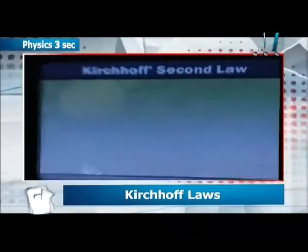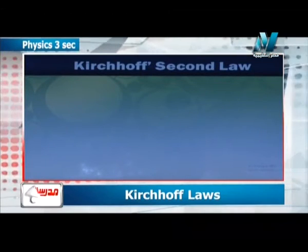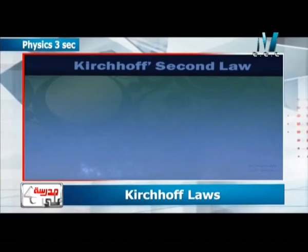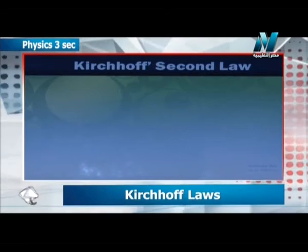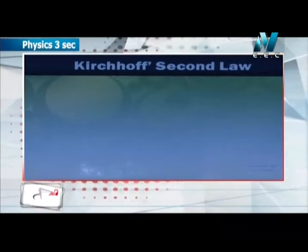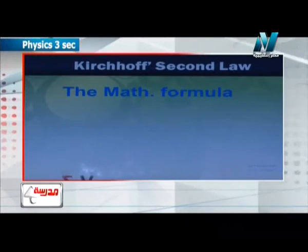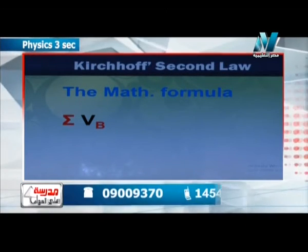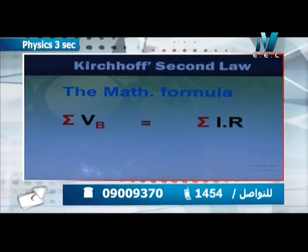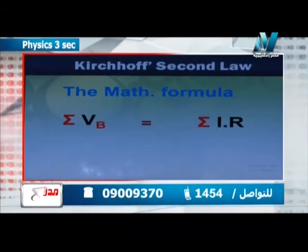What about the mathematical formula of Kirchhoff's second law? Very important question in the final exam. Each year he asks to write the mathematical formula of some equations. Okay, if he asks you to write the mathematical formula of Kirchhoff's second law, you have to write the following: sigma VB equals sigma IR. What's the meaning of sigma VB?